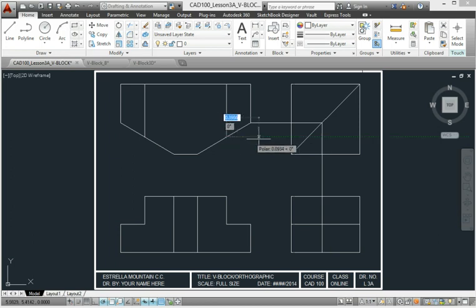We have a line here that needs to be projected over here, and it goes to here. The upper part of the feature is represented here, which is the upper half, which is this line. The lower half of the feature is represented here, which is the lower part of the line. As you look at our drawing, you can see what does need to be trimmed from our object. So we'll pick trim, hit enter, and remove the following parts. And now our top view, our front view, and our right side view is complete.